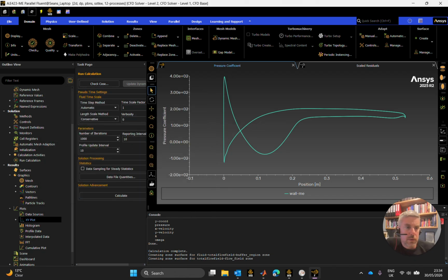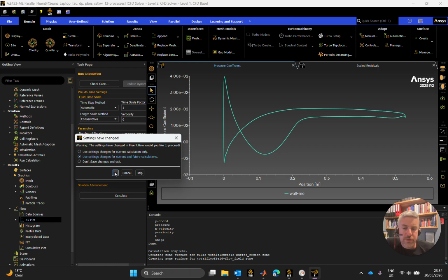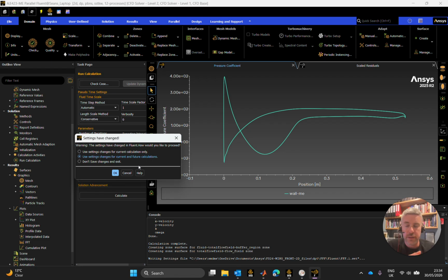All right, so what I'm going to do now is close down Fluent. I'm going to save this for future calculations. Yes, when this drops out, I'm going to save the file, and I'm going to go into the parameters. I'm going to assign the parameters that I just created in Fluent to be driven by the earlier parameters of the same specification that were created in Discovery. So I only have to change them again in one place, and then they'll filter through into Fluent as required.